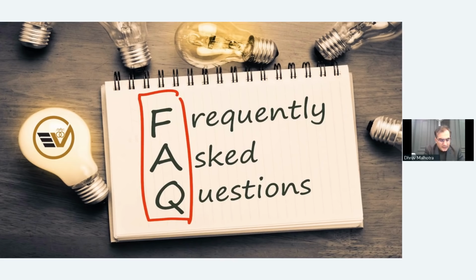Question number 8. Why does it consume more power when used with oil as compared to water being used as a sealing fluid? Like I answered earlier, oil has higher viscosity. Because oil has higher viscosity, it requires more churning power. And that is the only reason why higher churning power is required when we compare it to water.